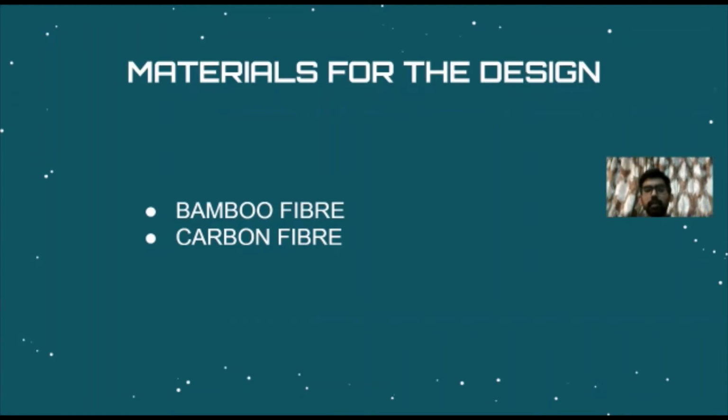Right now, bamboo fiber is used for the glider's skins, such as the wings and the fuselage, and carbon fiber is used for the structure. These materials are being used to make the glider greener and easier to decompose. Carbon fiber is used because it is safe, strong, and light, and bamboo fiber is used with epoxy resin so that the material is strong.